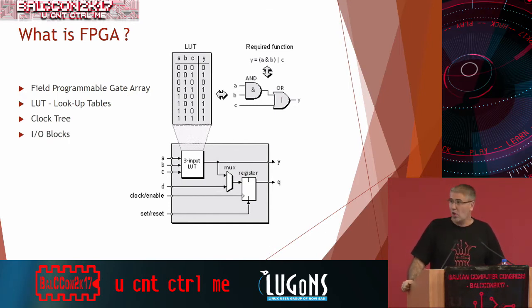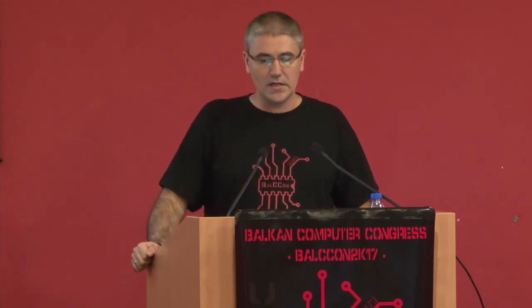Also, we have I/O blocks. I/O blocks are connected directly to the output pins of the FPGA, and you can define if that pin is an input or an output, and you can also put it on high impedance, for example if it's an output, and then you can manage the buses and so on.